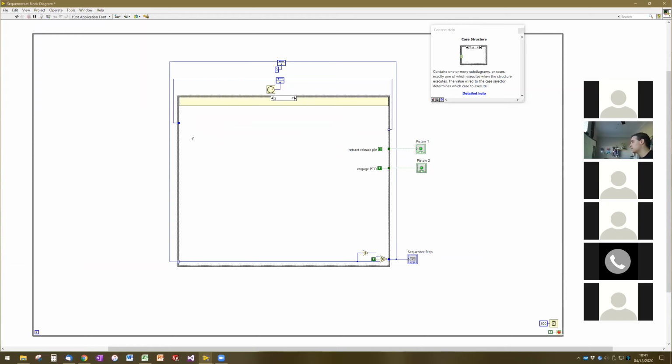Again, it's application specific. If you don't use another timer, it doesn't really matter. You could right click on this and type in 4265 and no one would care. Nothing bad would happen. Generally, the practice that I'd recommend is that when you don't have anything specific to do, you maintain the previous value. So just keep the time that we last saved in it. That way, if another coder comes back in later and wants to use the timer, it's a little bit more obvious what value is stored in the feedback node at any given point.